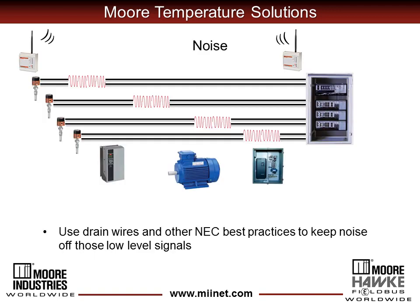Okay, let's consider some environmental issues. All of our plants have VFDs, motors, radios, and normal levels of EMI, RFI can cause errors in temperature measurements. Thermocouples and RTD signals are very low-level millivolt signals.